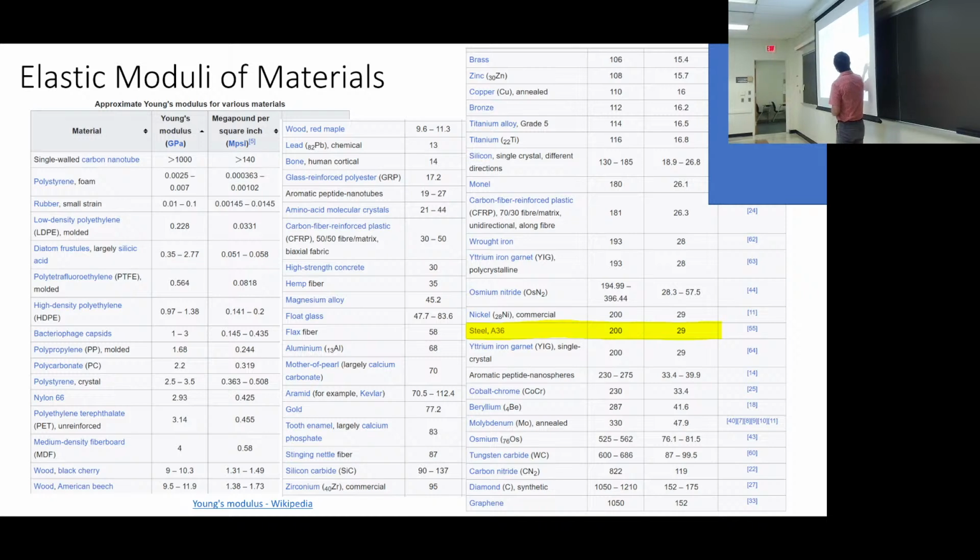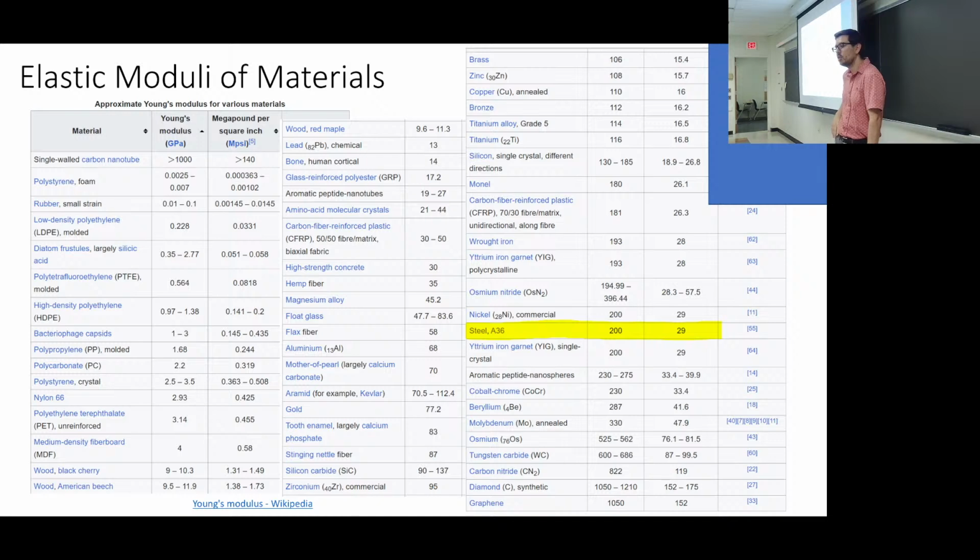Now, something that's kind of fascinating is the elastic moduli of steel and aluminum. They can have different alloys, different types. Their elastic moduli do not change much. So what you're going to find is that materials can have a wide array of strengths. You can tune the strengths of the materials, right? The yield strength. This is when they start to yield. But as you tune that yield strength, either through heating, through composition, through